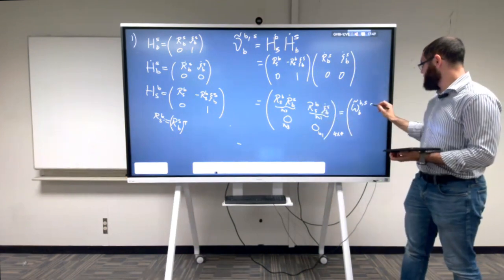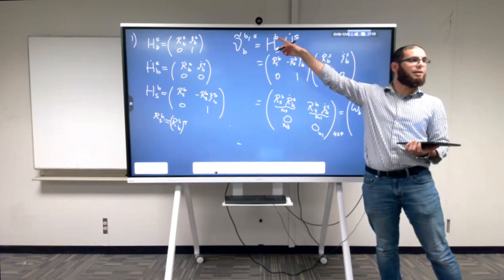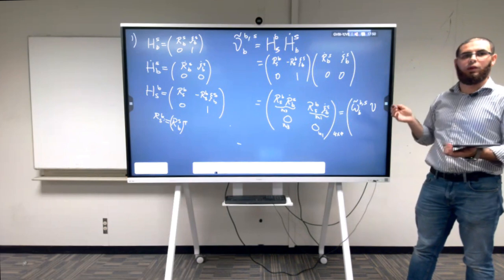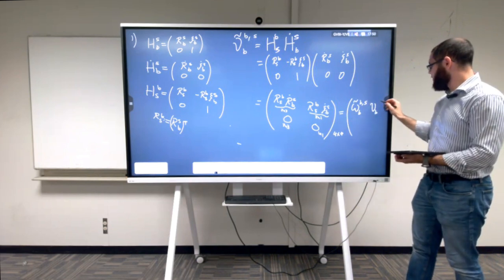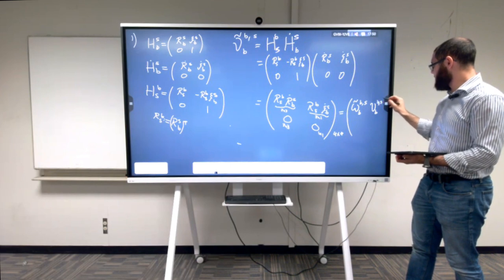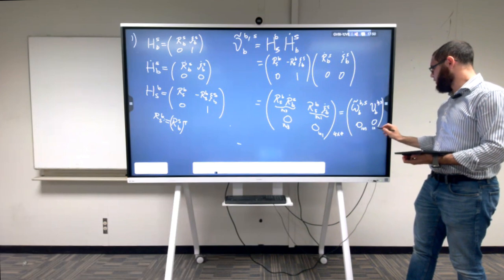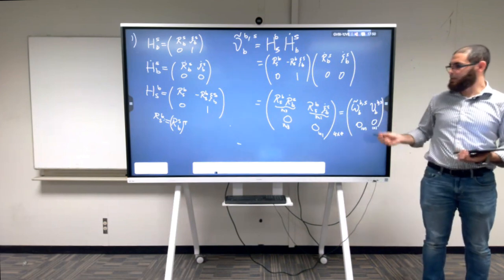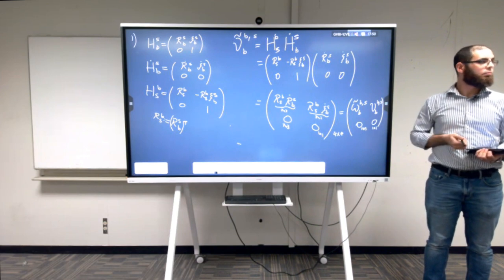So we're going to introduce this new variable, small v. This is different from the capital V. The capital V, we call it the twist. The small v is what we're going to be calling the linear velocity of frame B with respect to frame S expressed in frame B, and everything else is zeros. 1 by 3, 0, and a 1 by 1, 0. And this is simply what we call the matrix form of the twist.